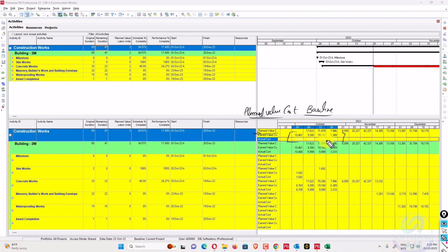Okay, so we'll update our Excel sheet and see how much percentage. We also need on our sheet these two percentages, like 17.49 and 34.577 to date. Then we can guess how much work we have done, and whether we are behind or ahead of schedule. From this percentage we can guess that we are behind the schedule. We know that because 34.57% was planned, and this one was actual. But how much delay? What will be our finish date?